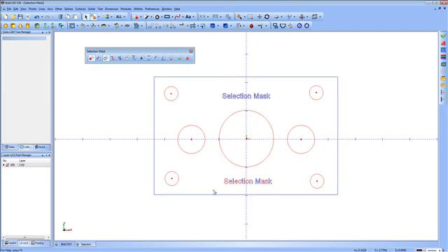the geometry as well. So to fix that, what I can do is come up here to the selection toolbar, right up here, and then I can go to the Add Remove feature, click the little drop down, and say Remove from Selection. What that allows me to do now is just window pick over this area, release my mouse, and that unselects everything. And then I can go back to the default Add Remove toggle.